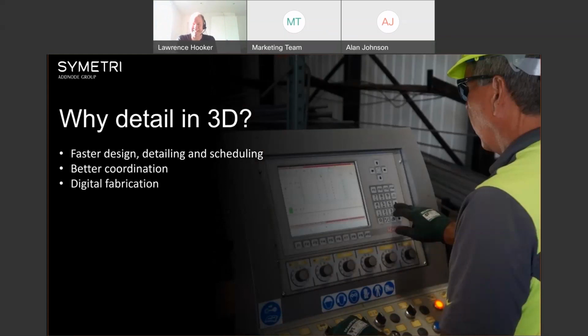The rebar fabricator can then take data directly from the model to CNC machinery using BVBS transfer rather than relying on manual input from paper schedules. Concrete pours can then be defined in the model along with instant volumes and quantities, ensuring more accurate management of material deliveries and much greater control, which in turn minimises waste and reduces cost.